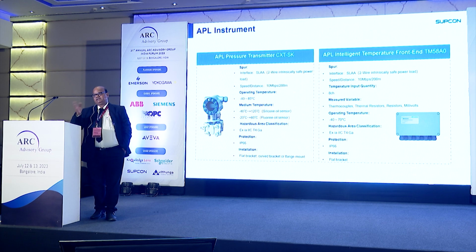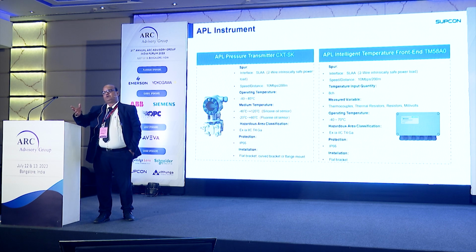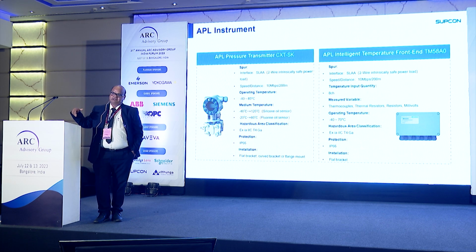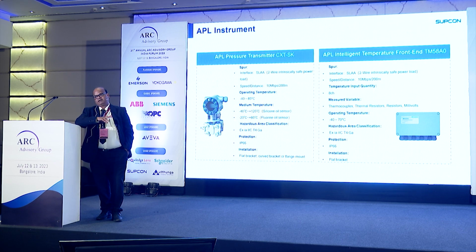In the boiler, waste to energy boilers are 4-pass boilers, not like a coal-based power plant where we have the single and second pass. We have 4 passes, and across these 4 passes, a single boiler has about 30 thermocouples at different locations to measure temperature. Now I have to put the thermocouple cable up to the JB, and from that JB, again take all this thermocouple cable up to the card.